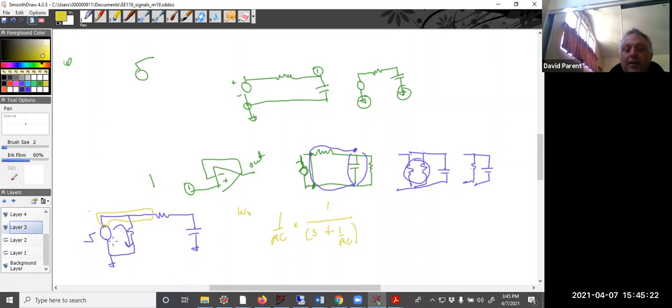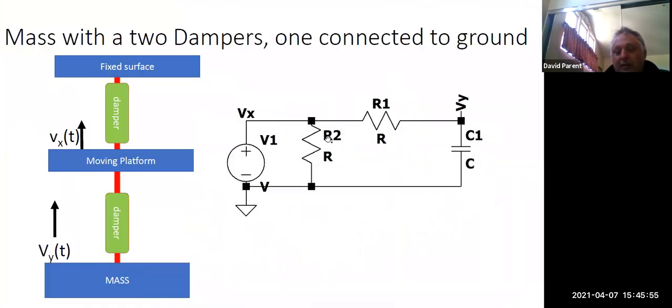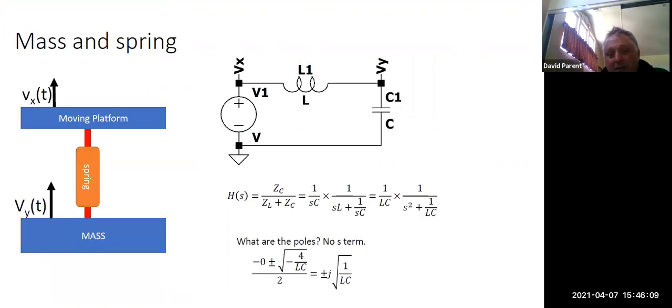Now, if you want to look at the natural response, short this. Let me short it more visibly. So now you could think of that resistor in parallel with a wire, and so the smallest resistance wins, which in this case is 0. And so then that resistor falls out of the equation. So either way you look at it, this resistor doesn't affect it. Now, if I had a small series resistance here, then it would. But if that small series resistance was a lot smaller than everything else, you wouldn't be able to see it.